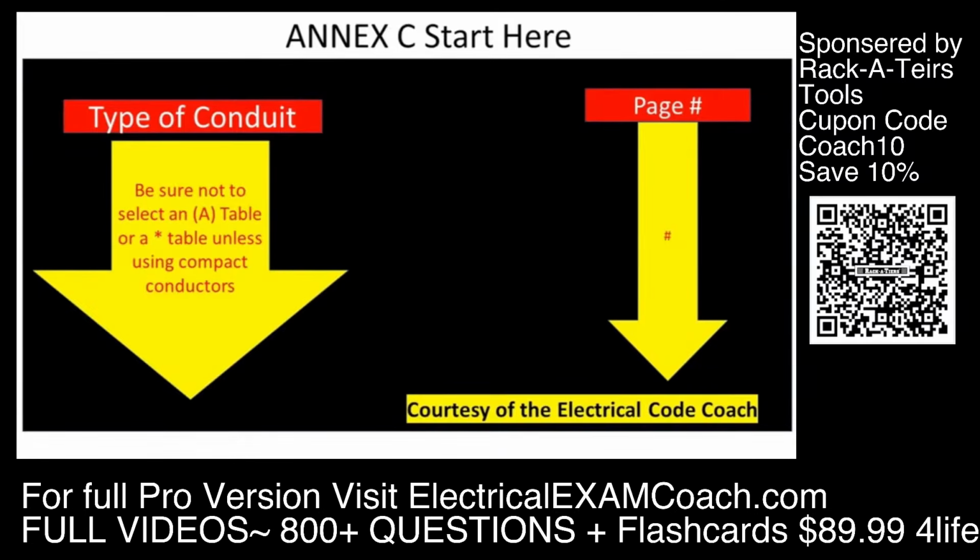It also is EMT. So what is the difference? And that's one of the most important distinctions that we have to watch out for with Annex C. The first version of the table, if you'll notice next to the C1, there is no A symbol. The A symbol signifies compact conductors. There are several different types of conductors out in the industry. Some of them are concentric, but the ones that are compact are bound a little bit tighter and you can actually fit more of those inside of a pipe legally.